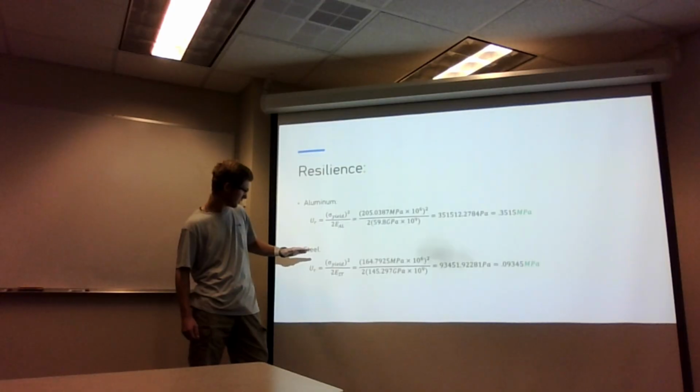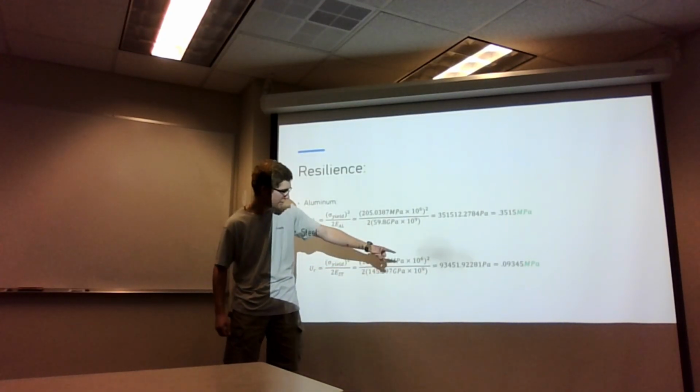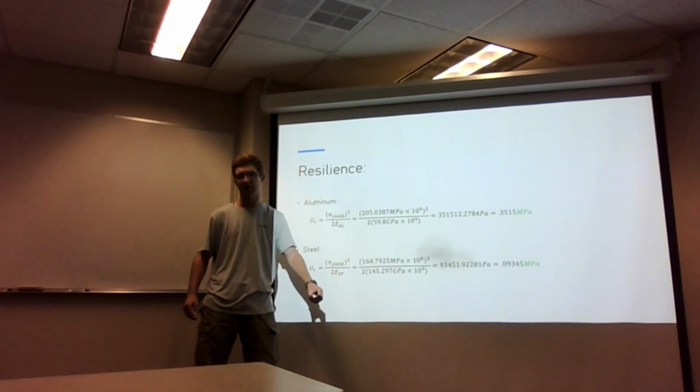Same thing for the steel. The yield stress, squared it, divided it by 2 times the elastic modulus, worked all that through, and came out to about 0.09345 megapascals.